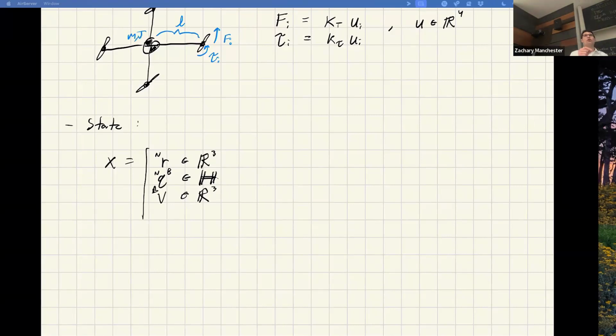when I do it this way, my errors are in the body frame, which is nice, because when I linearize this thing, remember, I'm linearizing everything. If my error state is in the body frame, that's the same frame my actuators are in, bolted to the quadrotor. When I linearize, there's no extra coordinate transformation in there from body to inertial. I've done that outside the control law in my error state calculation. Essentially, putting the errors all in the body frame means they're always lined up with their actuators, and the linearization works over a way broader range of attitudes.